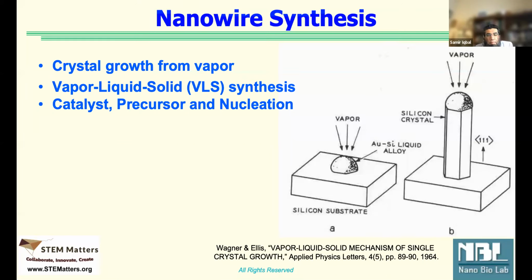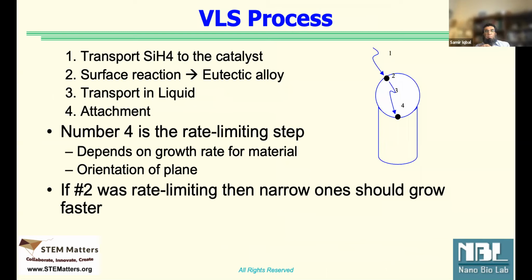The silicon gets absorbed into the gold. There is a process where they make an alloy with gold, and the silicon travels to the interface of the gold with the silicon wafer and the substrate, and starts accumulating, starts creating a kind of crystalline structure at the interface.